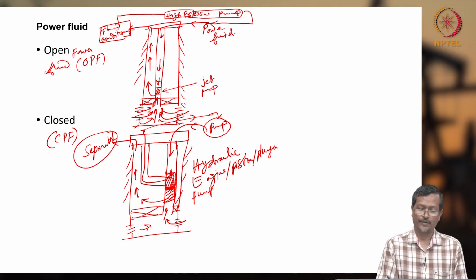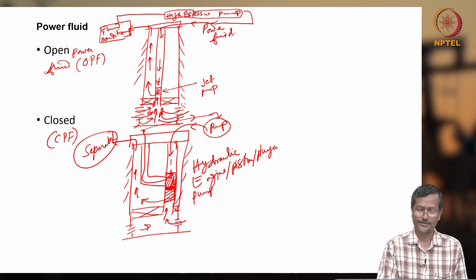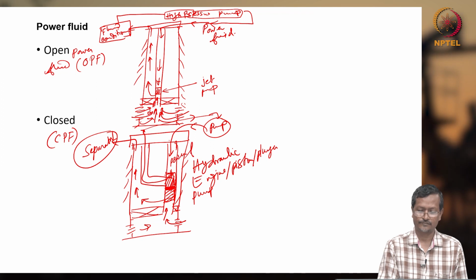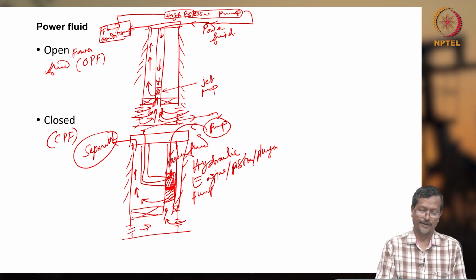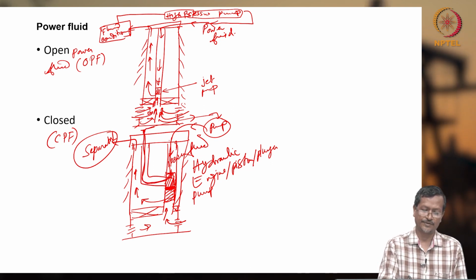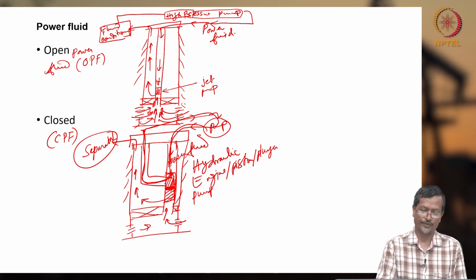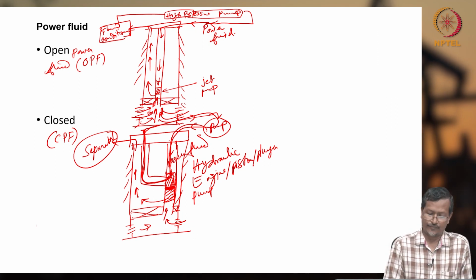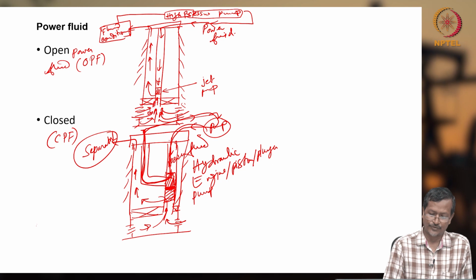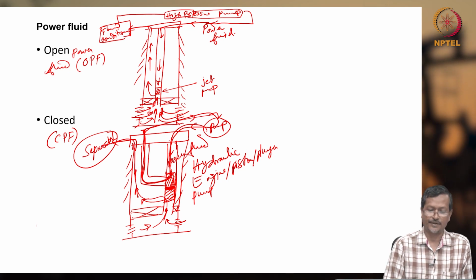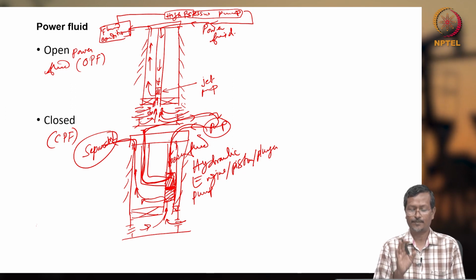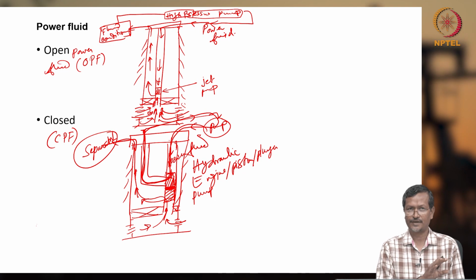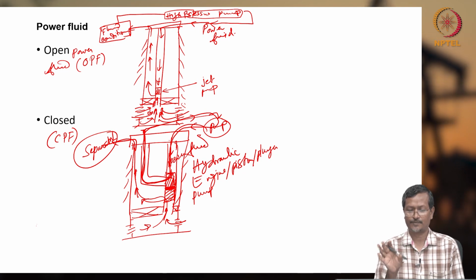So that pump will have power fluid. Okay, this is power fluid. Power fluid is coming from surface, it is going through the pump, it is not mixing, rather it is going up to the surface, again recirculating, going like this. And if I see this, wellbore fluid is going like this, and it is going to the separator. So wellbore fluid is not mixing with power fluid, so life is easier because you have only power fluid which is circulating, not mixing with anything. So you do not need to separate the power fluid.